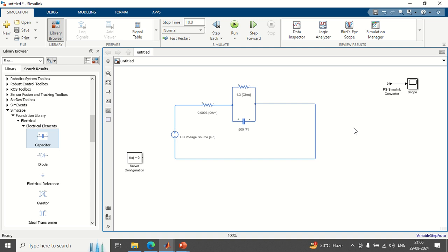So here what I am doing, I drew it, but what is essential that we need? In Simscape physical modeling, if I am doing electrical modeling, that needs an electrical reference connection, definitely and mandatorily it is necessary.